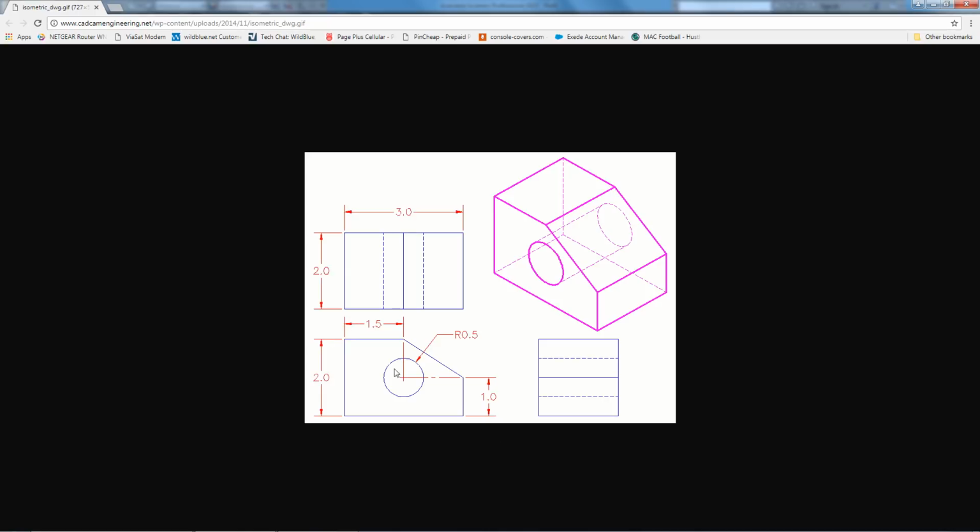So this is a situation where you're going to create all these other lines and then meet these two points. A good thing about having CAD software is that sometimes when you're trying to measure a real world object that you want to put in CAD, you can't find an angle, but you can find two measurements that lead up to that angle, and then you can connect the dots in an Inventor file. This can really help when you're going to machine something, and you don't have to know as much math, is really how it helps.